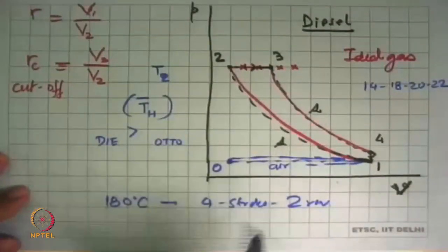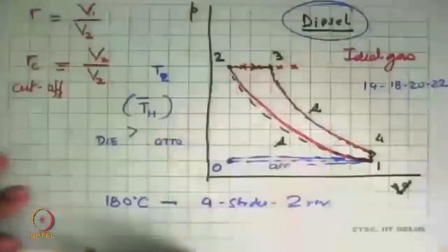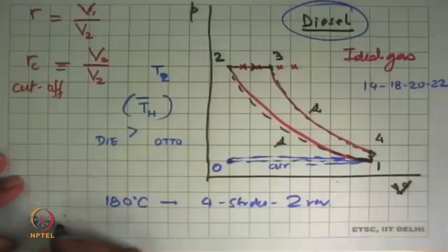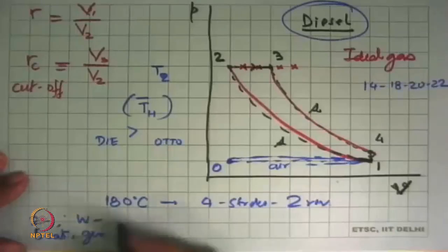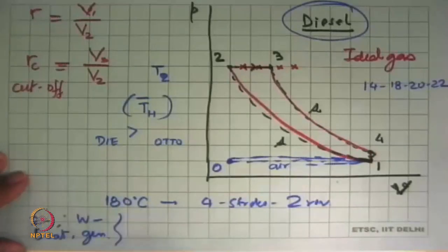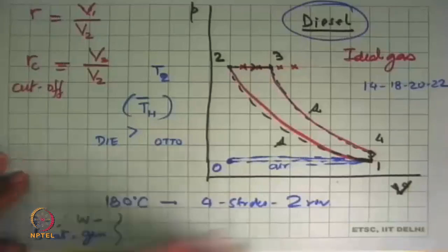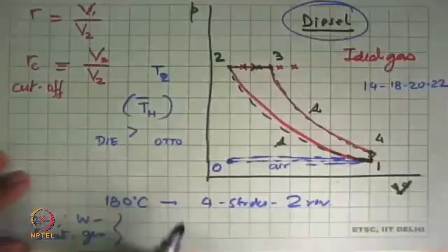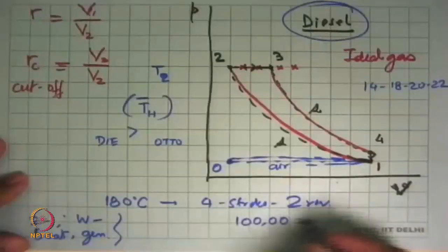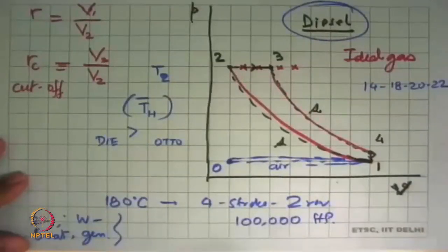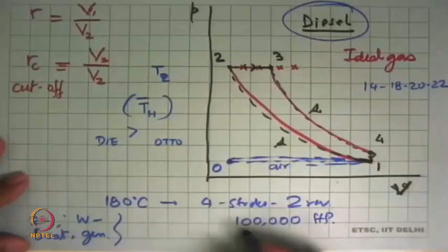The important thing to remember is that a vast majority of the horsepower that you get is from diesel engines. Petrol engines are very largely used for 2- and 4-wheelers, and in some cases for some types of boat propels, boat engines, and some generators. The capacities are relatively modest. 200, 300, 400 horsepower is about the upper limit to which one starts getting diesel engines. Diesels, they generally do not go to very small sizes, but on the upper side, the biggest diesel engines are like 1 lakh horsepower. And these are used largely in marine propulsion.